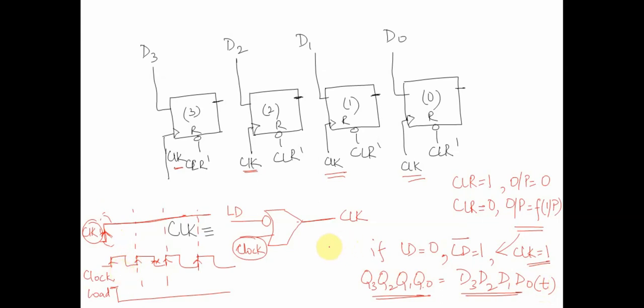And whenever a load value becomes 1, the clock will be behaving equal to clock, right? And in this particular case we will see a normal behavior where all the inputs are getting transferred to the output. I hope this is clearer, right? This particular concept is called clock gating. Basically what we have done is we have stopped the clock, but usually it's not recommended to do such kind of operations and to leave the clock as it is, right?